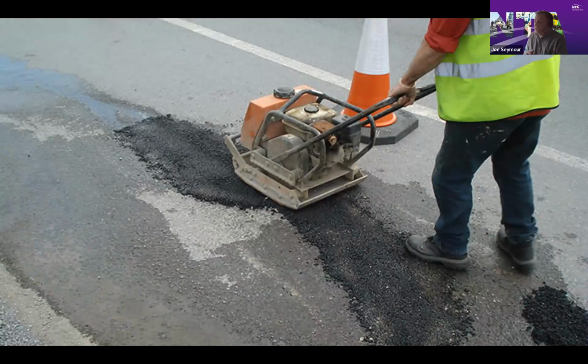When we're repairing roads, it's often put in a bit of delay set and you tamp it down and it's a bit rough, but the car will smooth it out over time. That doesn't really work in cycle tracks, so we need to come up with systems for the repairs within cycle tracks that give you a much more level surface. Or maybe we have to start looking at, if a utility comes through a cycle track, that they recover the whole cycle track and the section they've worked on. But it is a challenge we need to keep an eye out for, because this type of repair doesn't really work for cyclists, as the unevenness results in hazardous conditions for cyclists.